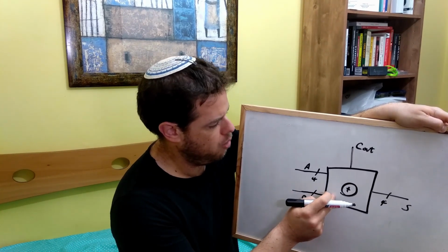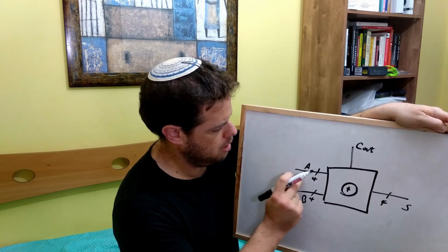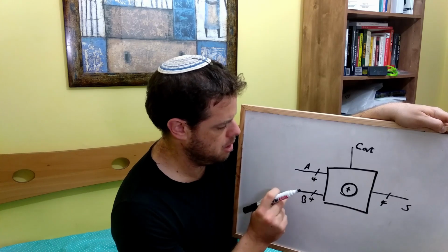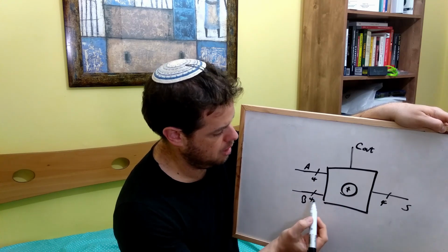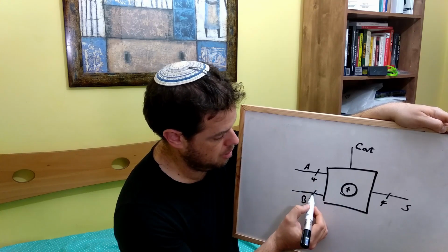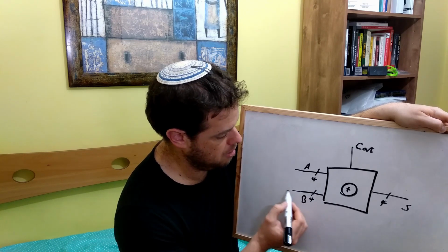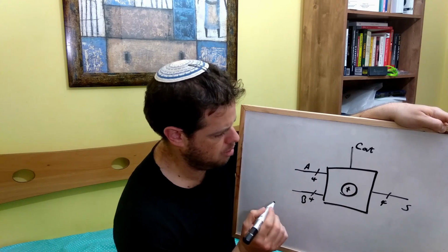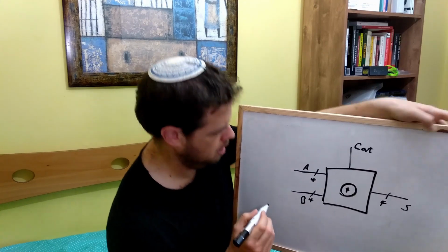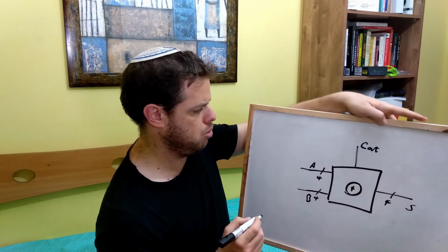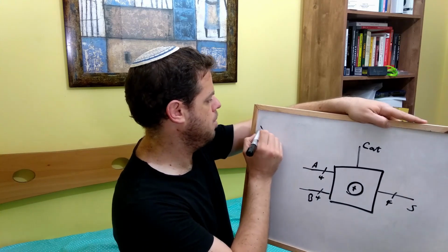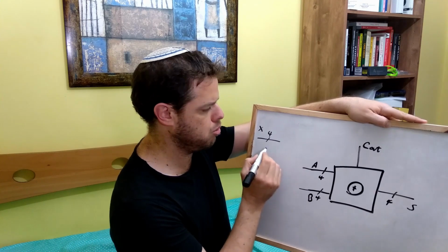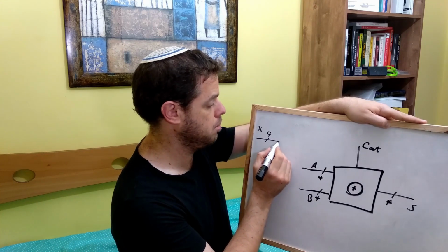Here we have our 4-bit adder, and you can see that it has two inputs, one output, but each one is a multi-bit input or output, which is what this tag here and the 4 mean. This is a 4-bit line, and this is a 4-bit line, and carry out is just a 1-bit line. And now let's assume that I have a number here, x. It is also 4 bits wide. This is also called a bus, a 4-bit wide bus.